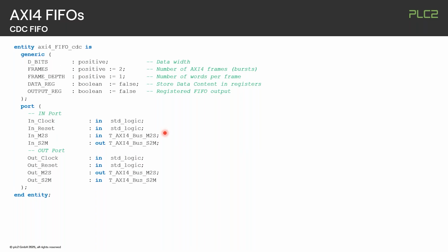This is needed in AXI. We have certain meta information that is conveyed with the AXI stream itself, like user bits, ID bits, and so on. They go into a separate FIFO data structure because here we need just 1 word per meta set. And the frame depth itself is for how many transactions you have in 1 burst operation. That's why we have 2 generics specifying it in here. Yep, that's mainly the interface for the FIFO that we have here.